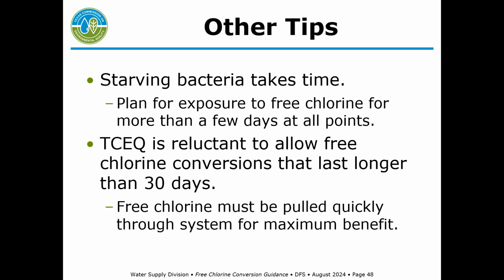So other tips, again, just repeating, starving bacteria takes time. Plan to expose all the parts in your distribution to free chlorine for more than just a few days. Like I said, as a rule of thumb, 2 weeks is a real good number to shoot for.